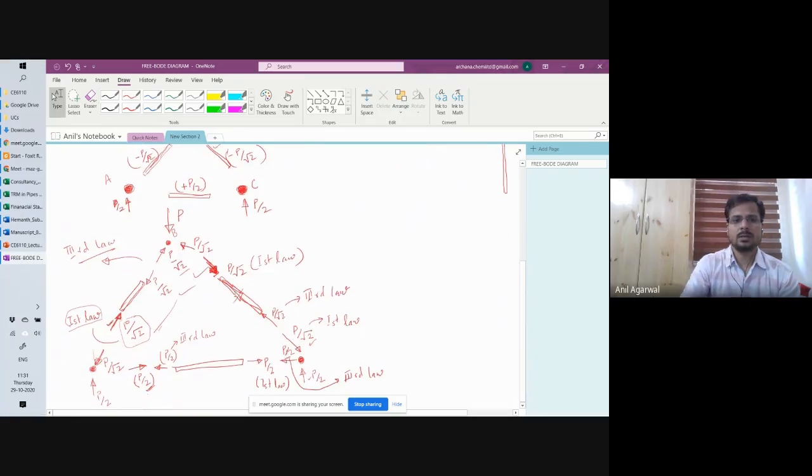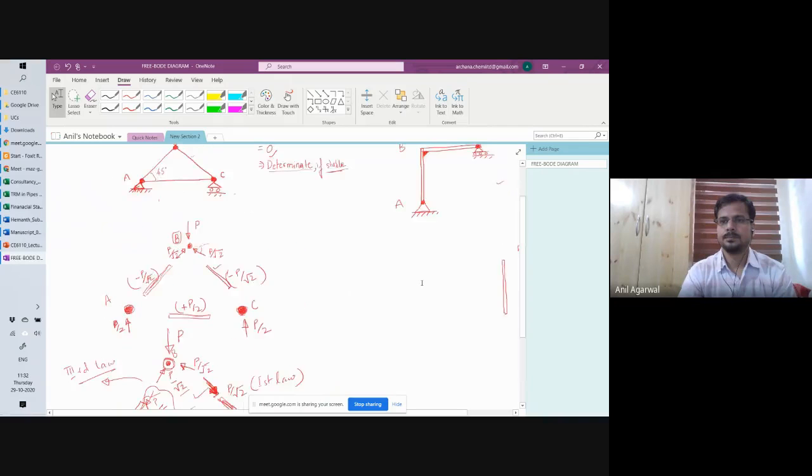So what I mean is that, see, on joint B, for example, here you can see joint B that I'm circling right now. On joint B, you have forces acting in this direction, right? P by 2 and P by root 2 you can see. But from here, if you can directly do the mental calculation and say that, okay, this corresponds to compressive force on the member AB, fine. But usually, if you are not that well trained, then it might be better to split it and show the forces on the member separately and say that, okay, yeah, this looks like a compression on the member. So once you draw this P by root 2 that I've shown here, then it will be very easy to visualize that, okay, this is compression on the member.